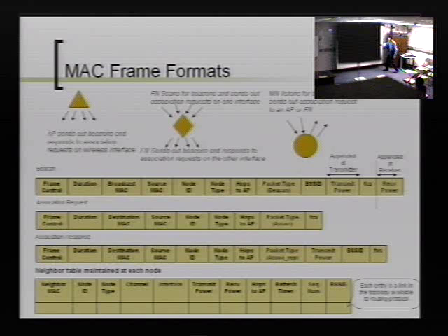So actually this is a beacon that we transmit. On every outgoing beacon, the node attaches a transmit power value, and for every received beacon, there is a received power that the node records. So this is how it can do it. In NS, it's fairly easy because from the path loss models we can reverse compute that. But I'll be talking about this a little while later.